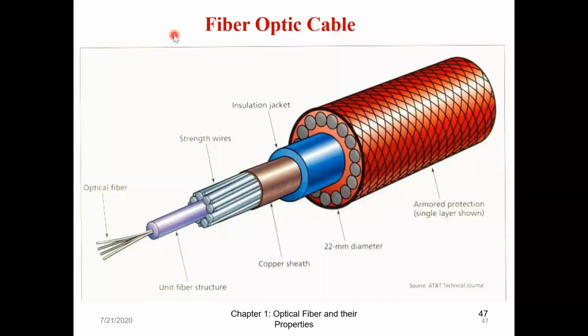Hello, ma'am. Doesn't it always increase the cost of the fiber cable? It increases, but we have to offer a series of protection because finally this is glass. Its tensile strength might be good, but with a little pressure, it might break. So I have to offer a series of protection, even though I say the fiber is cheap.